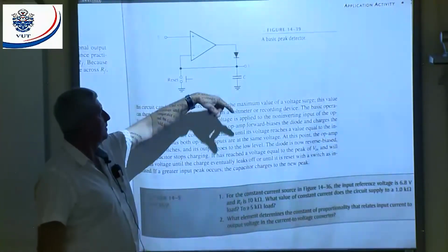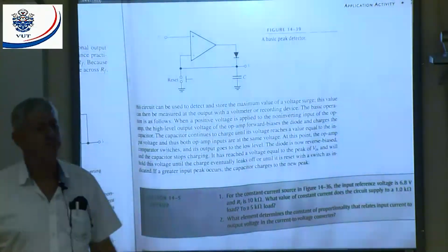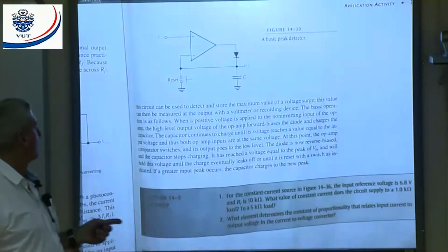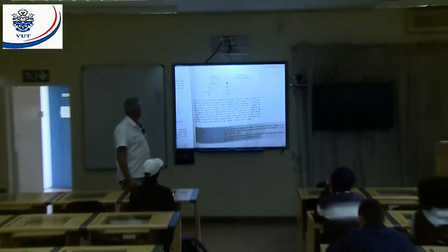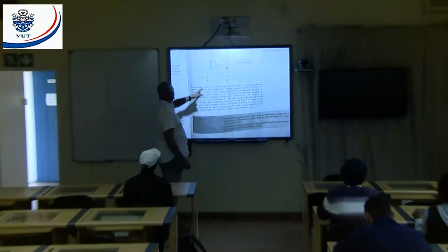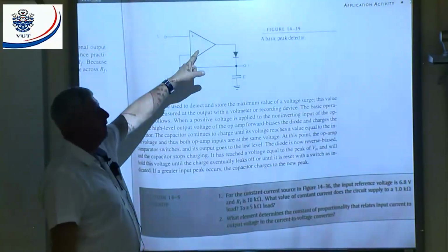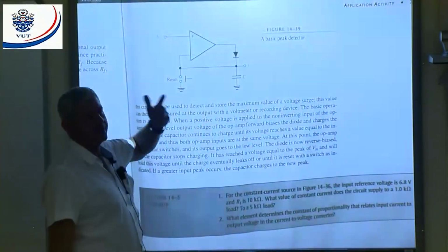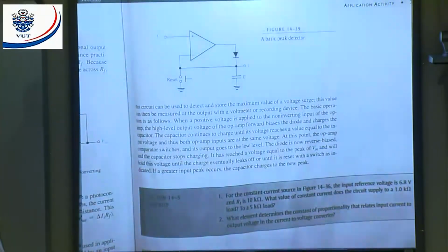Positive, all right. That means it will only work when I've got a negative input so the output goes positive. Isn't it another inverter, someone says? Oh, sorry, I'm talking nonsense. Hey, there's somebody that's awake here. That is a non-inverting input. What must I apply? I must apply positive, so the output goes positive.